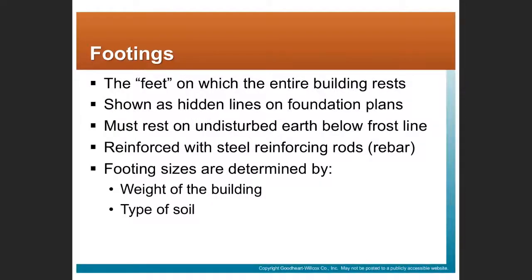Okay, let me just touch on a couple of things we talked about last week. Remember the footings, those are the feet, that's what the building is resting on. We see them as hidden lines when we look at foundation plans. And those footings have to rest on undisturbed earth below the frost line. There's rebar inside that concrete.